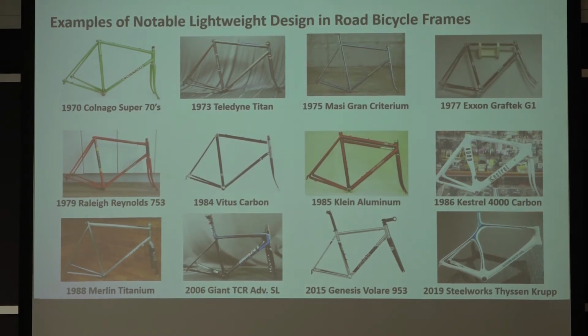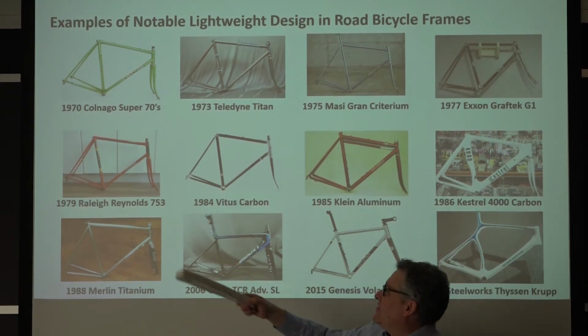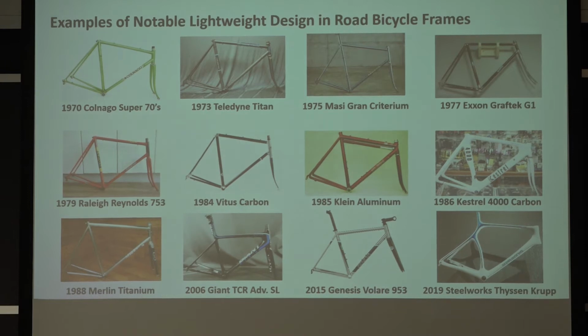They had some special test. If you were a frame maker, you had to take a special test to prove that you could weld or braze these tubes together without losing the heat treatment. There are actually some famous frame makers who weren't able to pass the test. So you don't see a lot of these Reynolds 753 bike frames because not many people could actually weld them. I think the steel was initially developed for making oxygen bottles for people climbing Mount Everest.